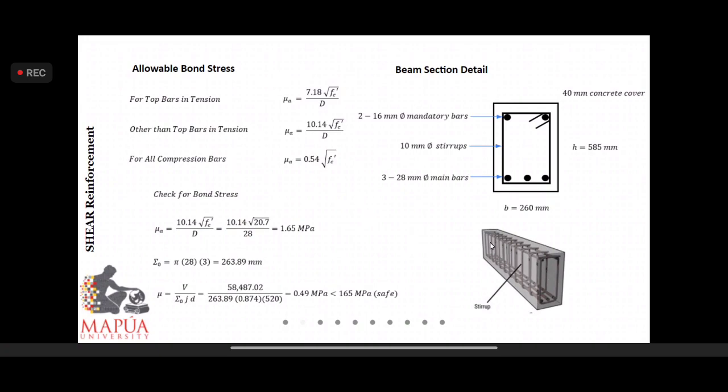Well, in actual design, we normally present nearer distance within the proximity of the support reactions here. So usually we set it up as 2 stirrups spaced at 50 millimeter, class A. Here 3 class A stirrups spaced at 100 millimeter, and among others. In the same manner, what you did here will be the same distances that will be provided.